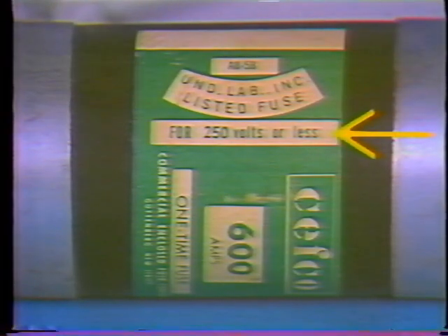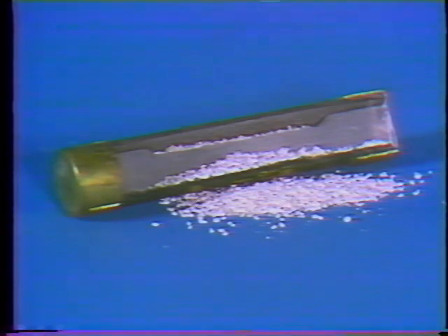The voltage rating is the maximum voltage that the fuse can interrupt without having an arc remain across the open section in the fuse element as the element melts. An arc, quite simply, is the flow of current through air between 2 points. When the fuse element melts, an arc forms across the open section. If the voltage in the circuit is higher than the fuse's voltage rating, the arc will not be interrupted and current will continue to flow through the circuit. Some fuses are filled with a material such as sand, which can quench the arc when the fuse blows.